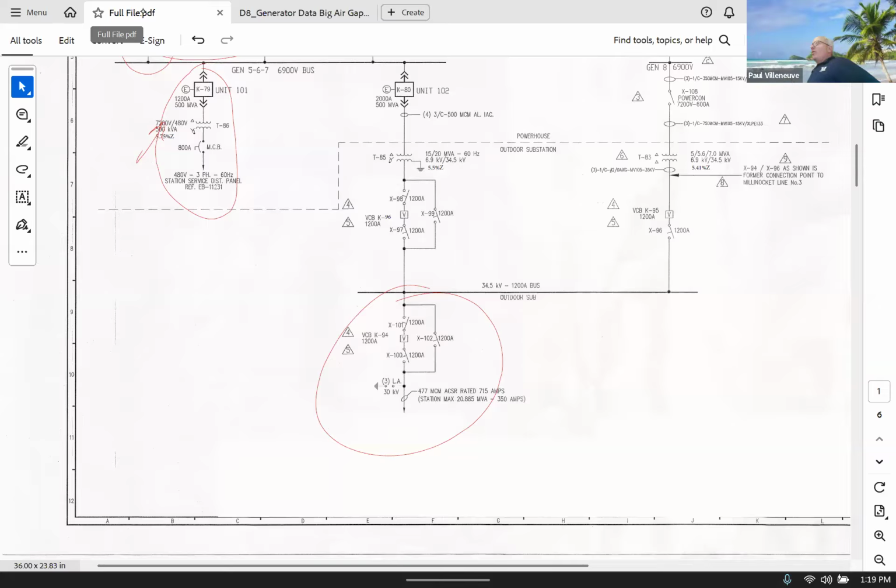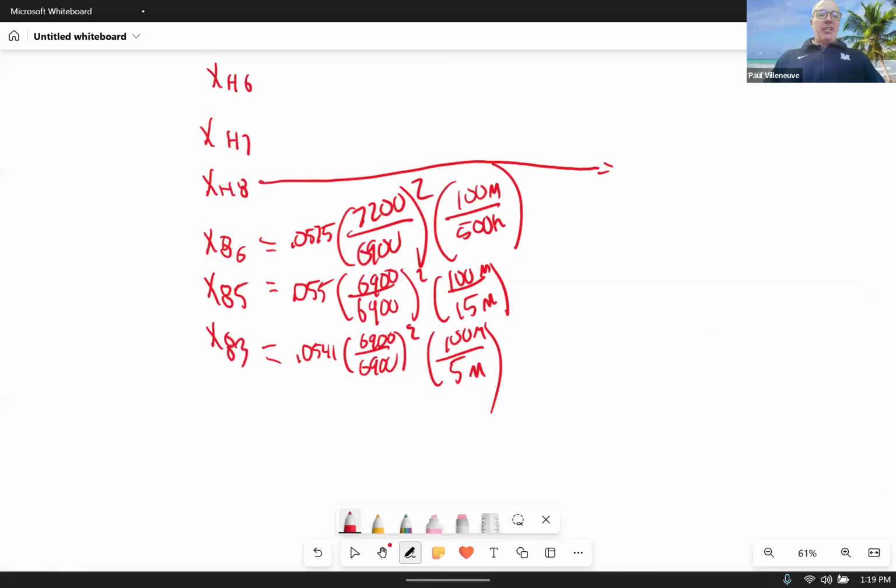Right? So remember where you get the original equipment ratings, you get them from the nameplate. This nameplate transformer takes 7,200 volts and steps it down to 480. Okay, I was thinking that you were talking about T83 and it's at 6,900 volts. I think I said that incorrectly, but then I swapped these around, right? I call that 83. Yeah, it was just the one transformer that changes base. Correct. Well, it changes voltage base. All the transformers change power base, right? Correct. Okay.